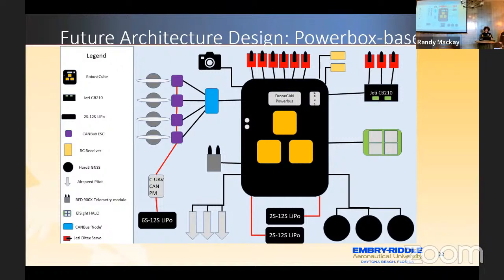That way you could run something like 16 servos and have that power supply, which didn't burden down a carrier board, and then have plug out auxiliaries for something like, in my case, a drone CAN power bus. So you could have maybe 4 different drone CAN nodes, which it could provide power to.